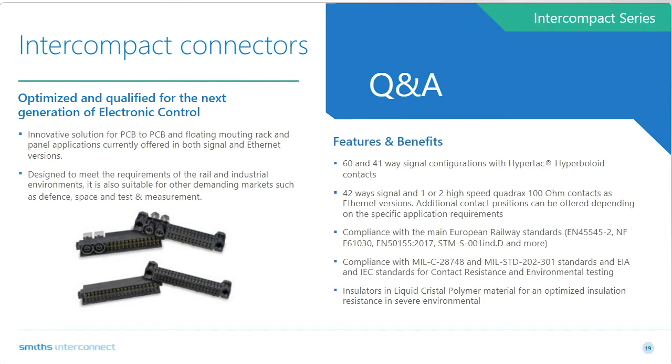And if you look into the rest of the connector, for example, the higher misalignment from a floating arrangement standpoint, the higher voltage with the number of contacts packed in a smaller body, the PCB to PCB and rack and panel application configurations, and finally meeting the whole list of compliances. When you put all of them in one big bucket, it's genuinely very difficult to find exactly like-for-like connectors out there in the market.